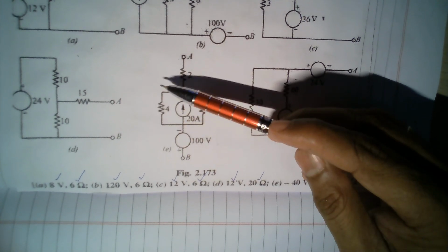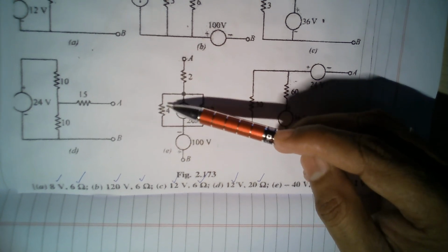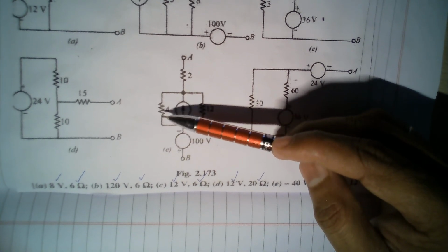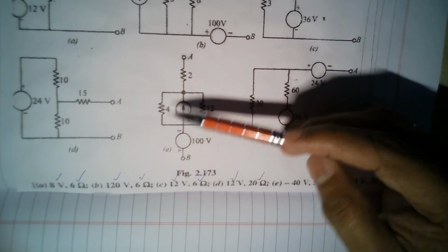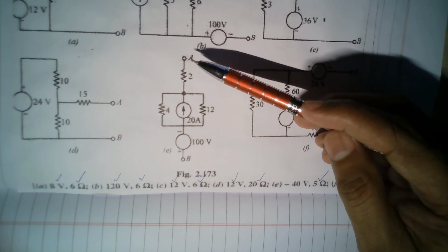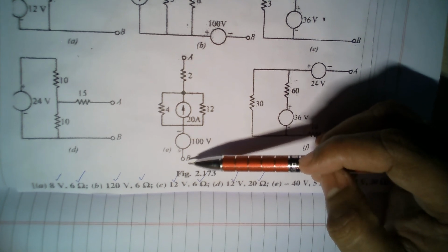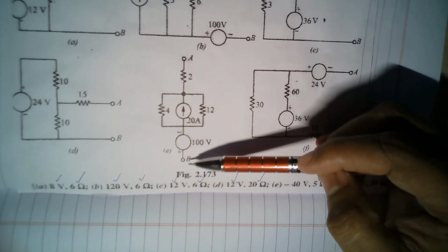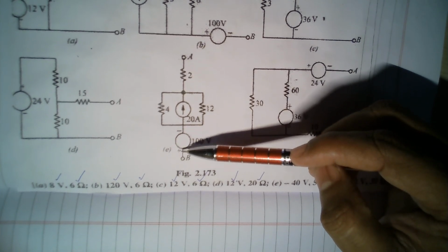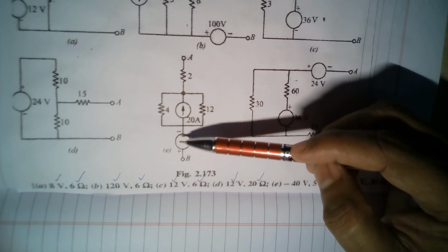Okay, so remember that this is plus and minus, and the drop here will be 60 volts. Now apply Kirchhoff to find the Thevenin's voltage. VTH is nothing but VAB. It's nothing but KVL from B to A. So you start from B. First you hit the positive terminal, then you go towards the negative.